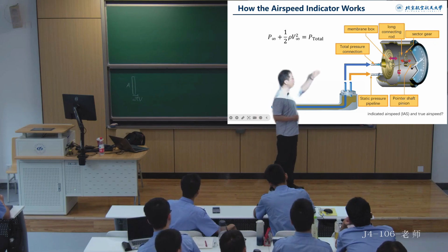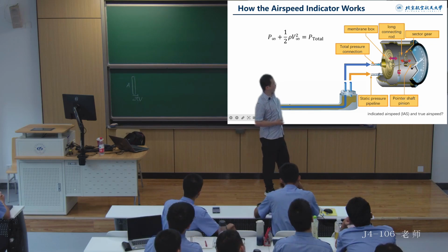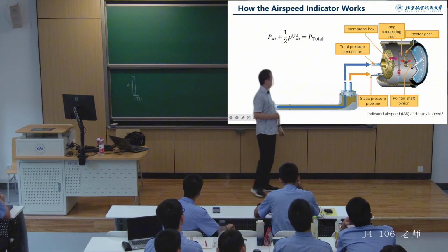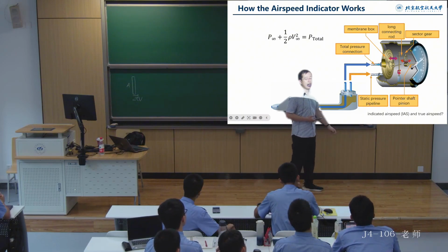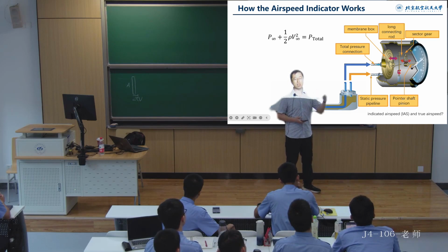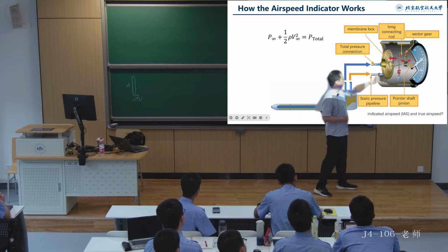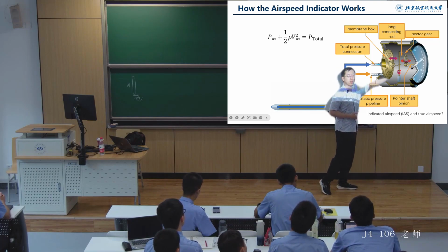It also consists of an airtight casing with a sealed diaphragm structure, as long as the air pressure inside the casing differs from that inside the diaphragm. The diaphragm will correspondingly expand or contract. This expansion and contraction of the diaphragm are used to drive the corresponding mechanical pointer to rotate. In this way, the airspeed of the aircraft can ultimately be displayed on the gauge.